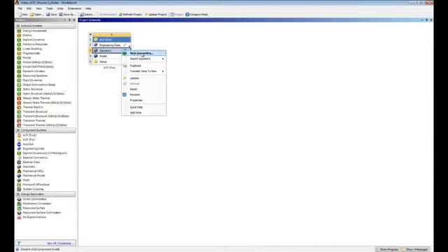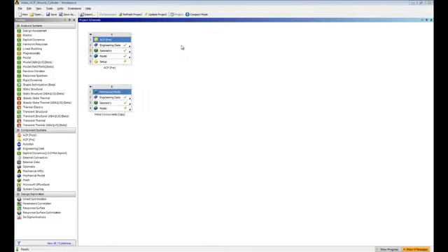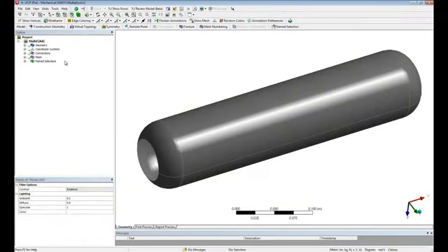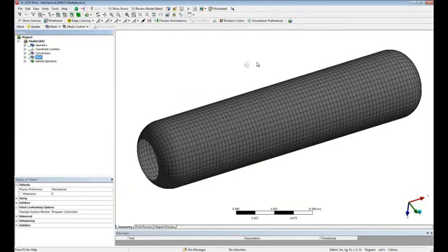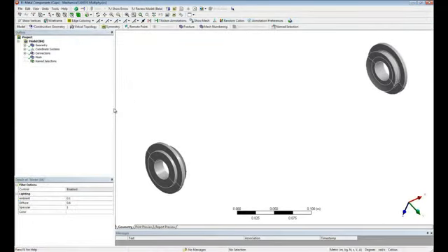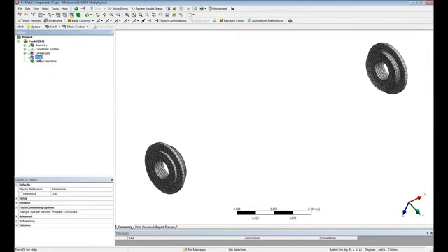So here we are just choosing one material and putting it into our project. Then the next thing we do is define the geometry we are going to use. In this case, we are going to take the file that corresponds to our pressure vessel, and we are also introducing a second system that will contain the non-composite parts. If we look at the composites model, we see that we start from a shell mesh, which is kind of the mold we would use, so the internal skin of the pressure vessel. And the second model has the two titanium caps that we are going to assemble with our composites model.